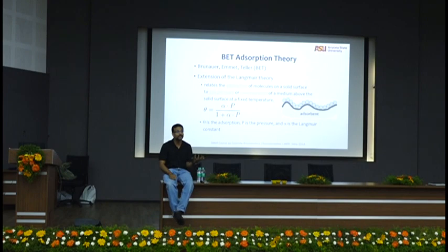And that's a method. Which gas do we use? We don't want it to be interacting with cement paste. What gas do we use? Nitrogen. If you don't want it to react with anything, you use nitrogen. So BET surface area is measured with nitrogen. Nitrogen is good because the size of the nitrogen molecules is also much smaller than the size of the particles that you're interrogating, right? So you're sending nitrogen into this complicated structure and expecting it to stick onto the surfaces,